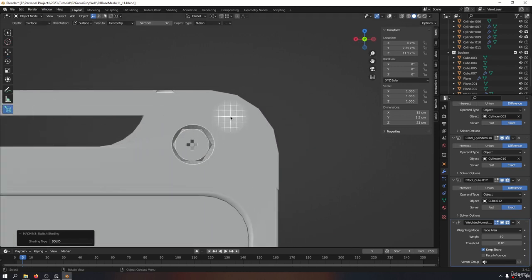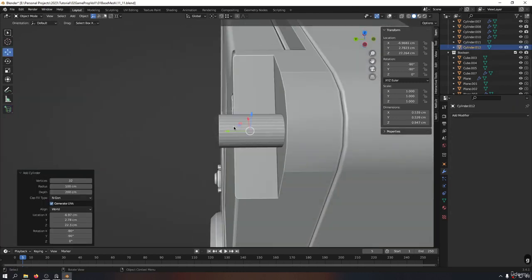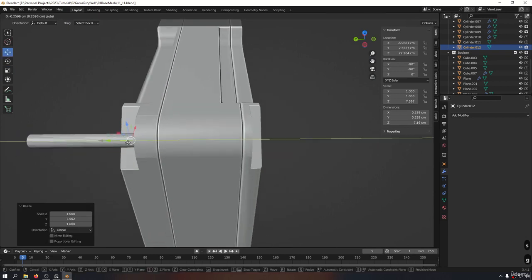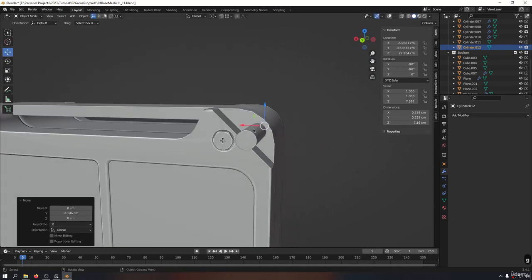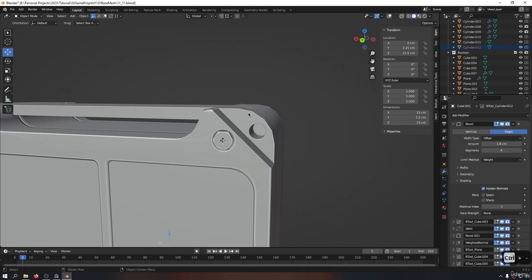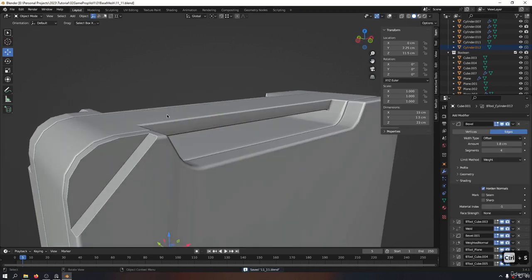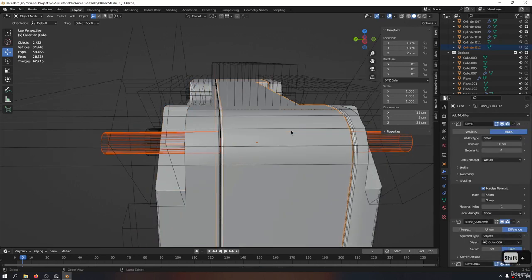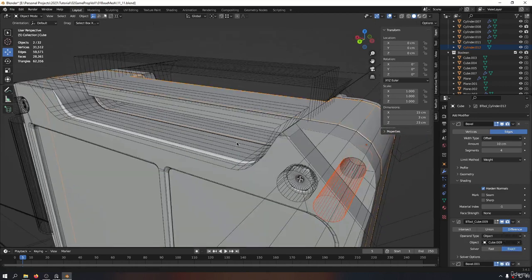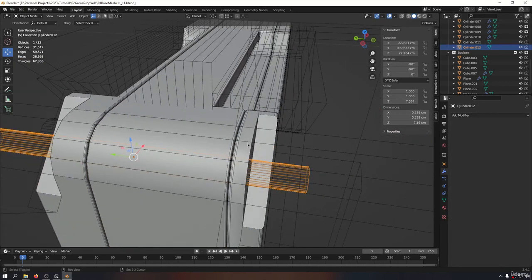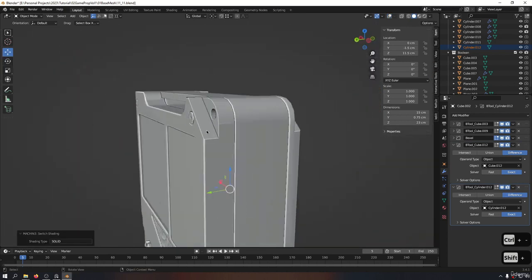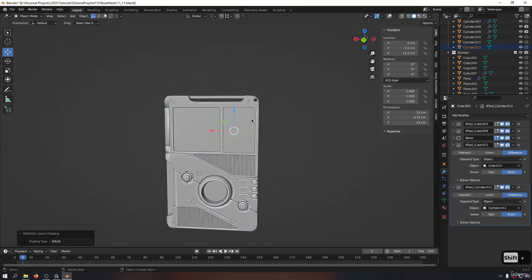And now let's do another tertiary detail on this. And again, I'm bringing this cylinder. I'm going to cut this cylinder all the way to this side. Okay, let's bring that here. And then I'm taking this one, Control minus. Okay, perfect. Of course, in order to cut that all the way, we need to take this one and select these other pieces as well, because these are different pieces and need to get the Boolean applied differently. Okay, now let's take a look, and we see a cut through here, which is perfect.